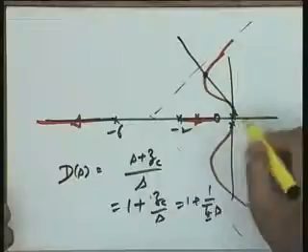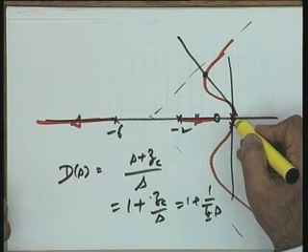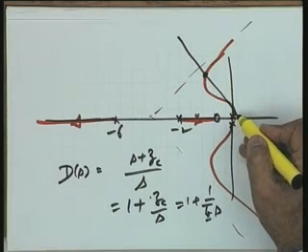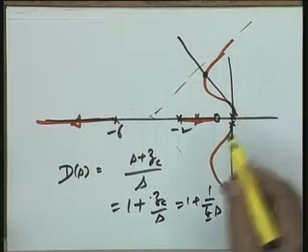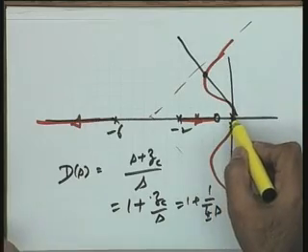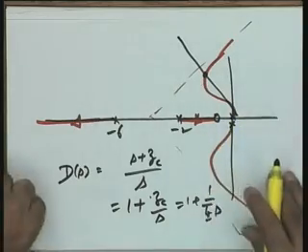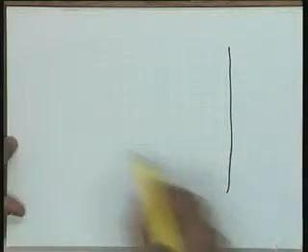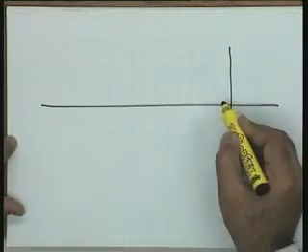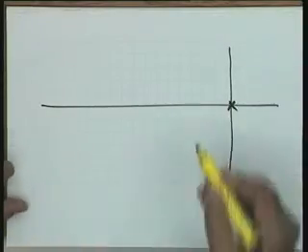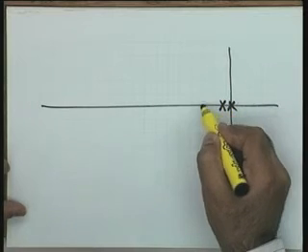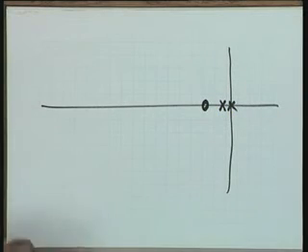Now, the question is this, the last point I want to mention: what is the need of jumping to this particular requirement of Kv equal to infinity when the user does not need it? You see, the pole at this particular point has totally destabilized the system. So, the design requirements can be appropriately met this way: this was your original pole, you make your pole here and a 0 here.